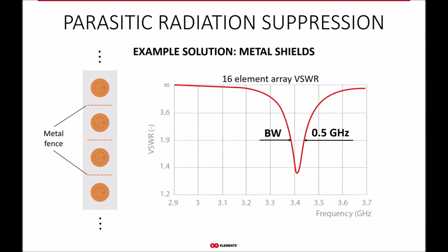This amazing side lobe performance comes at a price, though. On top of the more complex structure to manufacture, the non-resonant nature of the feeding structure and the presence of the air core make this antenna rather narrow band, which is not a problem, of course, depending on the application. But again, for WISP networks, 0.5 GHz bandwidth is simply not enough. Another factor preventing widespread adoption of solutions such as this one in the WISP industry is actually the end price. This is not the simplest structure to manufacture, which boils down to increasing the cost to a level not many WISPs would be willing to pay.